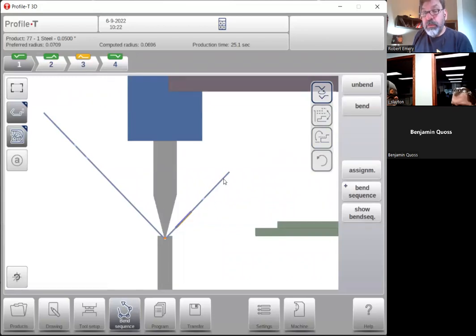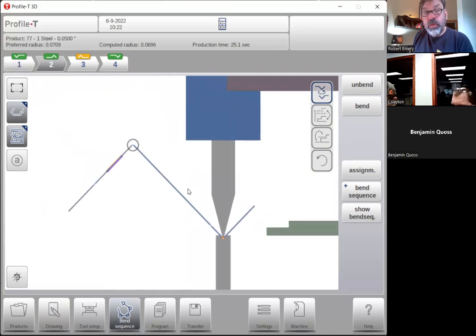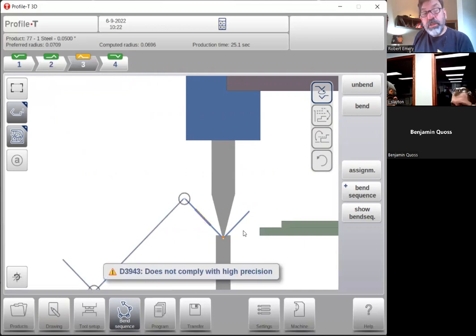So far, so good. Here's bend 2, no problem yet. Any variation of the blank should be over here. Uh-oh. But then when I do this one, I can't guarantee it because you're holding that flange. I'm really guaranteeing this flange. So that's the issue.